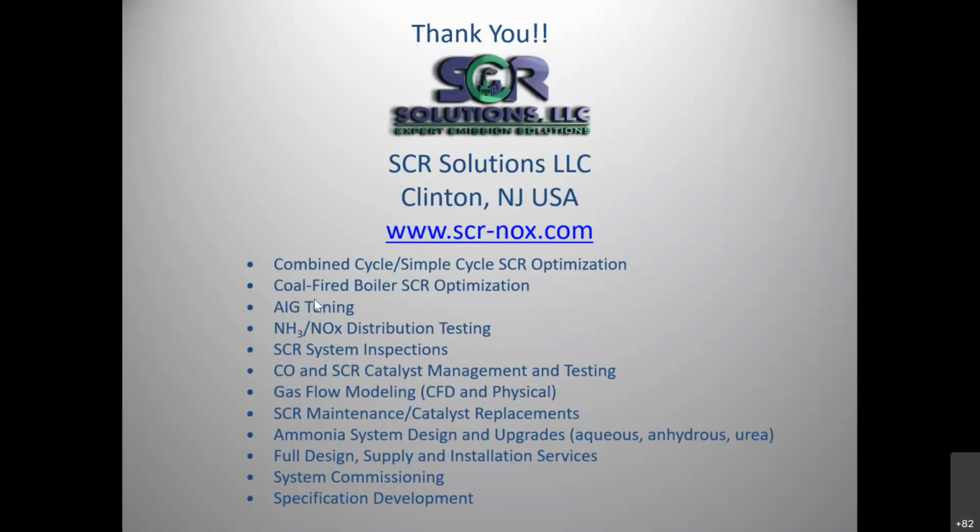Thanks, Barry. Bill, you had mentioned in case study number 1 that the customer was having trouble with AIG plugging. And those are pretty impressive RMS numbers down to 6%. If the pluggage continues, that RMS number, of course, naturally will go up and deteriorate some of the gains that were made. What was done to address the root cause of that pluggage, and does the customer need to do any periodic maintenance, or is there a trigger that they watch? Maybe it's simply ammonia slip or something else that initiates that periodic maintenance?